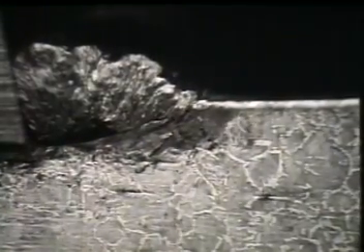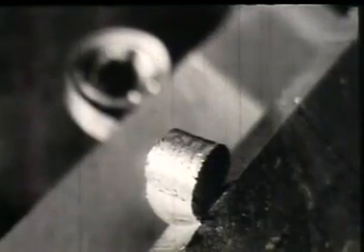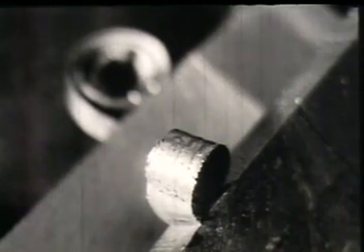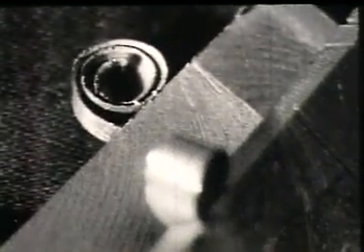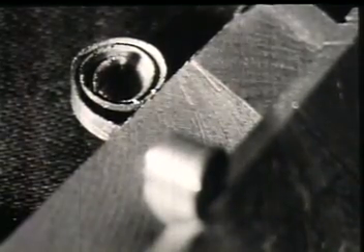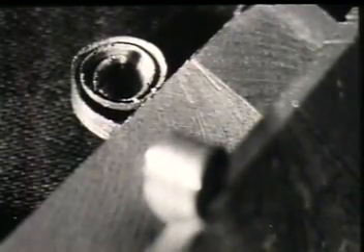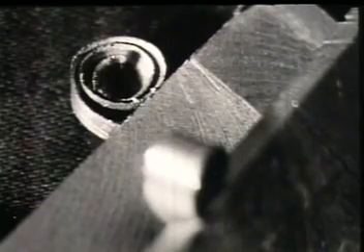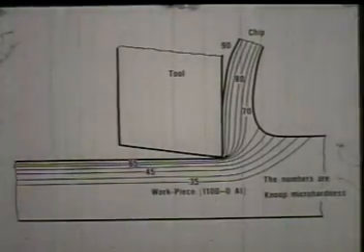If the cutting is stopped while a chip is being formed, and the chip and surrounding workpiece are carefully cut out from the bulk of the specimen, it can be metallurgically examined. After polishing the section sample, micro-hardness tests can be conducted around the chip. The results of such a study on a chip of aluminum is shown in the sketch. After a large number of hardness readings are taken in both the chip and the specimen near the tool, a distinct pattern is evident.